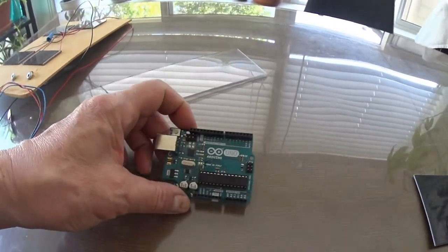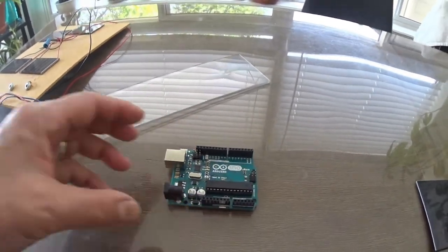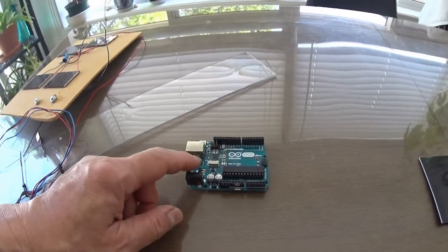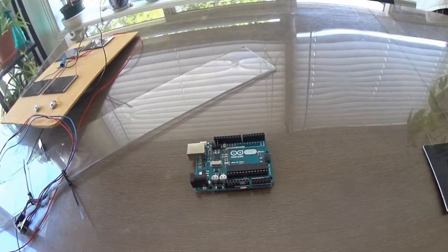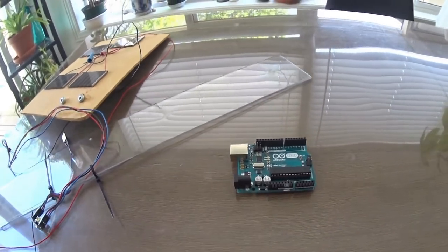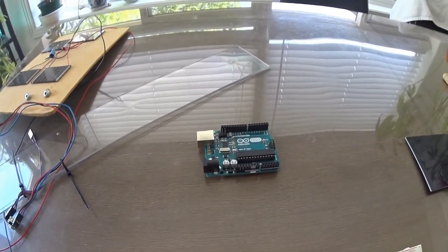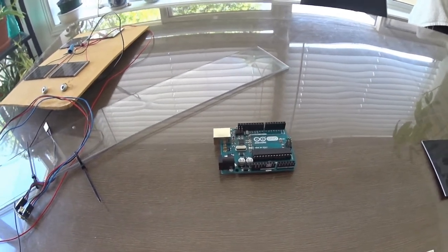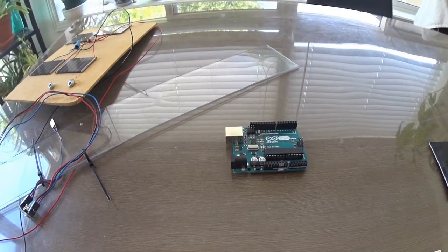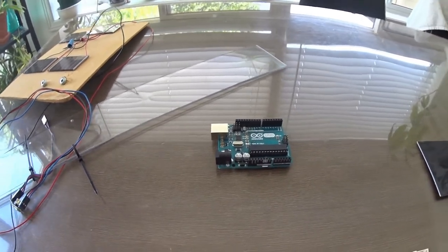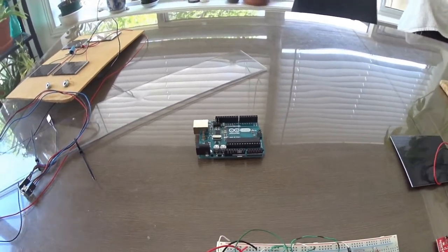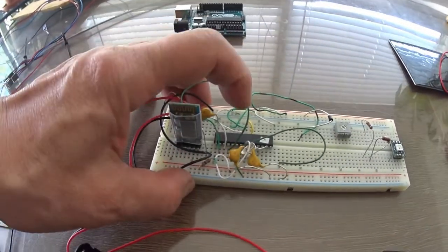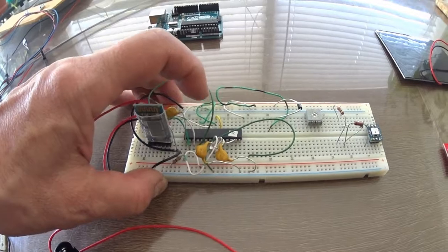I did start with a simple Arduino, but the big problem with the Uno is these LEDs that are on there. Those LEDs consume a lot of power. They would drain my batteries within half a day if I didn't have solar charging going on. So I need to go to a low-powered version of the software. So I had to go to the bare-bones Atmel processor.